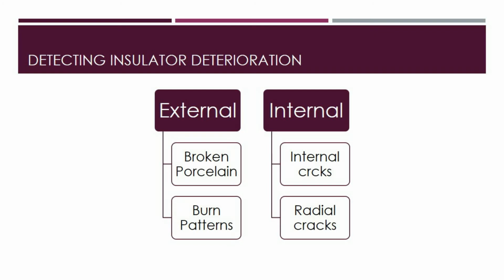A glass fiber reinforced rod is usually covered in either EPDM or silicone rubber weather shelters with appropriate end fittings to make composite insulators. While composite insulators provide a wide variety of mechanical strength and are far lighter than other forms of insulators, the EPDM silicone rubber substance is actually soft and readily cut, ripped, or punctured by sharp objects, and the sheath and weather shelters must be in good working order.